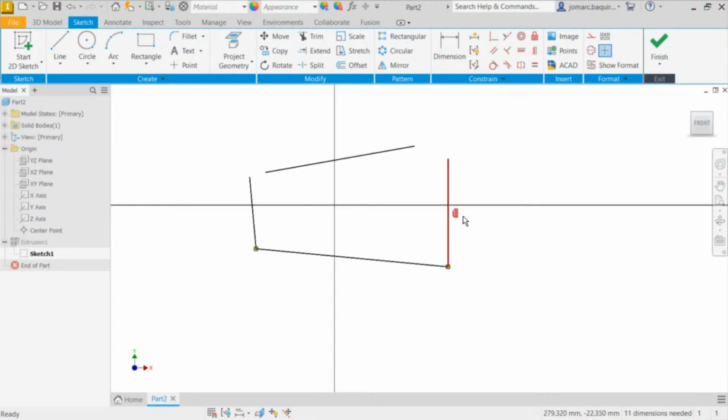So if I want this not to be perfectly vertical, I can head over here, select this vertical constraint, delete. And notice I can make this diagonal. Okay? So let's add constraints. First one, let's discover coincident. So coincident, I prefer this endpoint and this endpoint to be linked or touching each other, or coincident with each other.